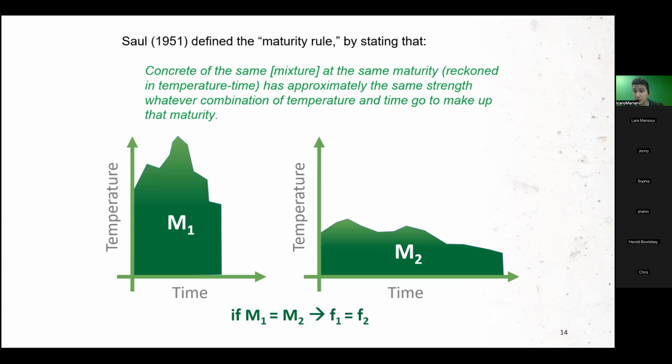Absolutely. And the opposite can also happen. Let's say you are in New York City and it's 20 degrees outside, during winter. What happens is if you take those samples and put them in a very nice warm bath of 72 degrees, and your structure is actually at 35, 32, you just see that dissipation very rapid. What can happen is your samples are overestimating what your structure is actually doing. So you're actually using the sensors for safety purposes, not only to gain time and money. Does that make sense? Yep.